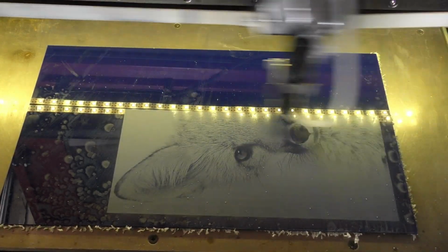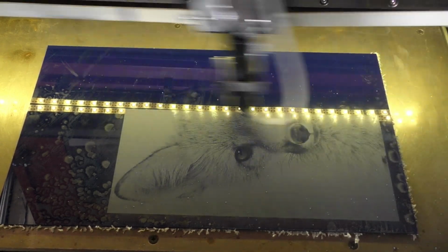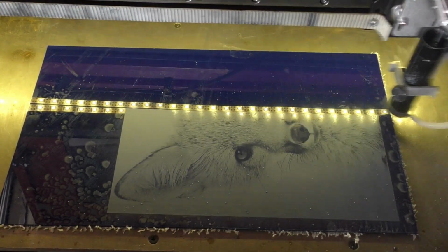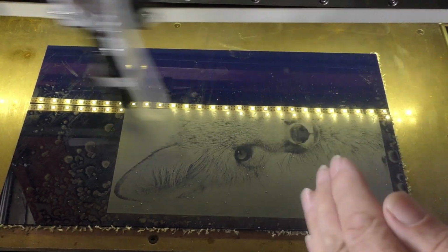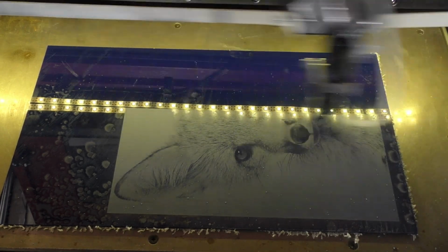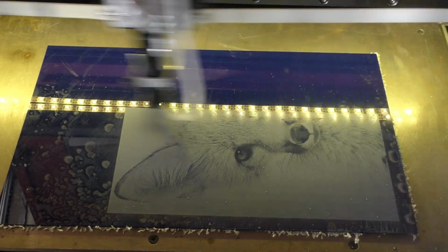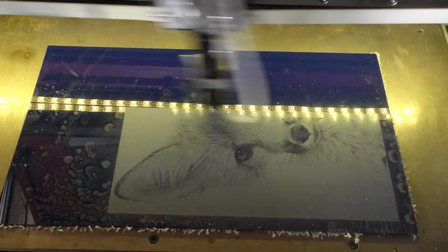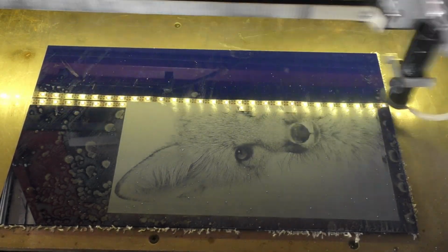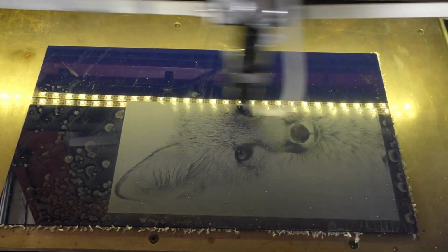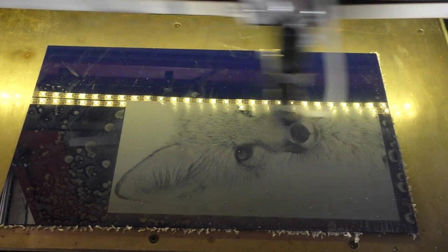So basically I've used my checker pattern to do 2 things. First of all, to try and get rid of the aliasing, and secondly, I've been very accurate in the way in which I've set my scanning offset up, because my scanning offset is now set to better than 0.1 of a millimetre. In fact, it's set to 0.05 of a millimetre. I'm running this at the settings I use for my checker pattern, which is 1000 millimetres a second as opposed to 1200 millimetres a second, which I did for the first one.